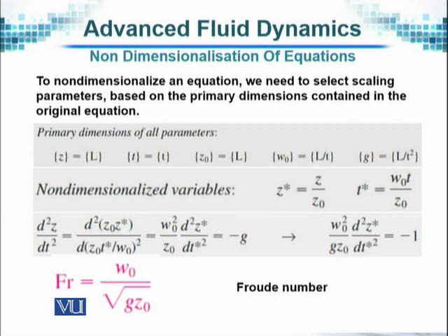So for example, if pressure or velocity is not playing any role in an equation, then how can we use pressure or velocity to non-dimensionalize it? So the relevance has to be there. It has to be a typical representation of the equation, and then we use it in a sensible manner if we want to get sensible answers.